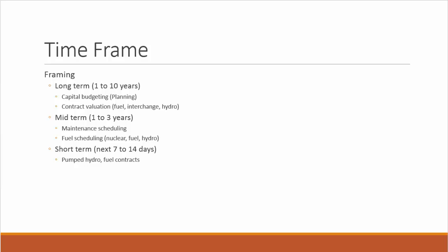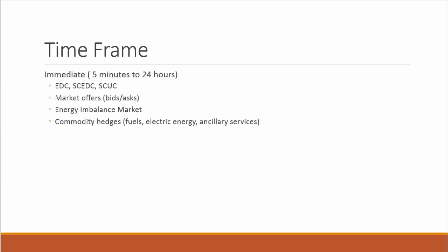Of course, if they've underbought, what they must do is decide how much fuel to buy to maintain reliability without getting into much risk of having to go to interchange contracts. So our work in this text is primarily in the unit commitment area and the maintenance scheduling area for the next 14 days, although we can stretch this out to the next year for operational planning.